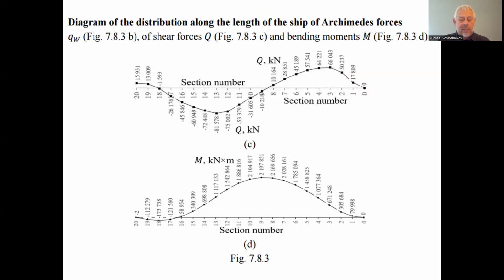Okay, so this is the result. Sorry, let's talk a little bit about how we got this result. This result for the transverse force and the bending moment diagram is drawn on the stretched fiber. So this is a negative bending moment. It corresponds to the shape with the bulge upward, due to the cargoes aft and the ballast and the stocks in the fore part of the ship, and the excess of the buoyancy in the middle part.